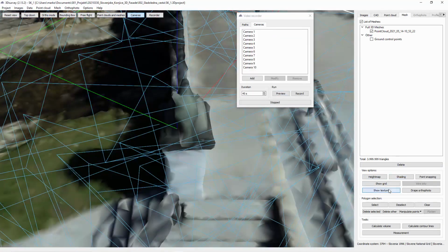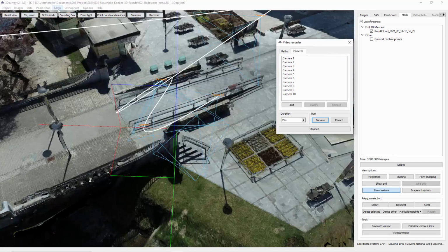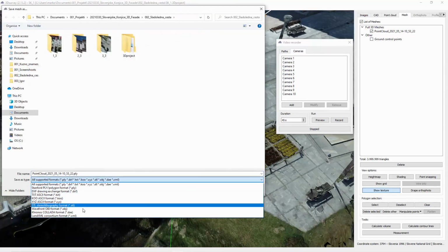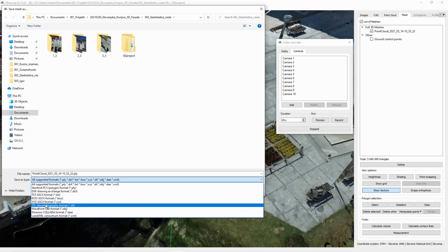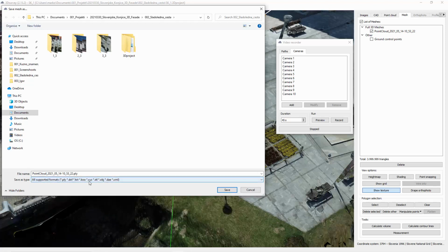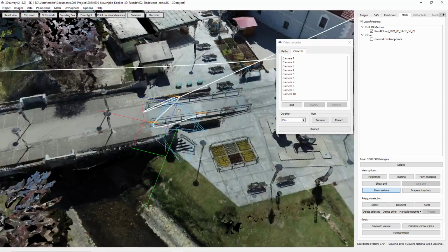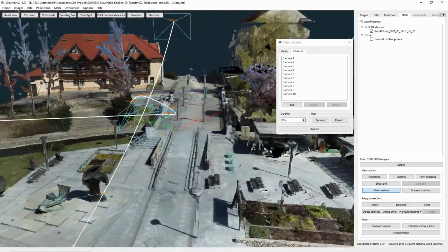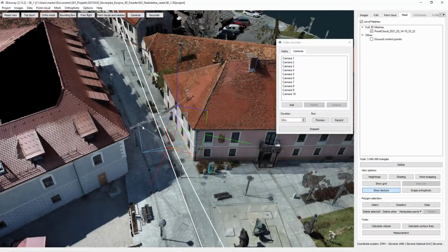Okay, let's stop the recording. The end result of this is, let's go to mesh, save as, and set OBJ file format. You could also use Collada, STL or something like that, depending on what your partner wants to have. So we have a broad range of export options. This was my second example, mapping the old city town, and hopefully you get a good idea how it works.